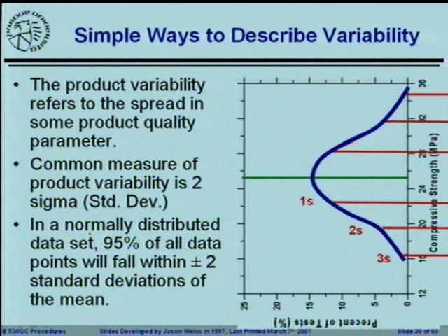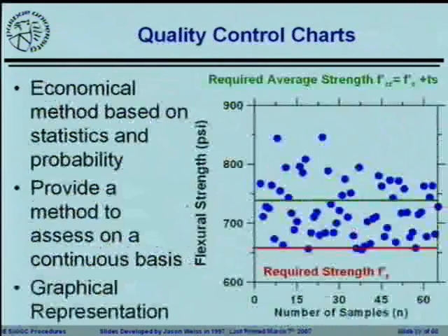So this gives us a little bit of information on where we are when we start to talk about the mean value. So this is our mean value, the green line. And then we start to have our 1 standard deviation line or our 3 standard deviation lines. And a lot of times we're going to use things like 2 or 3 standard deviations as really our outside limit where we start to want to do some sort of process control.